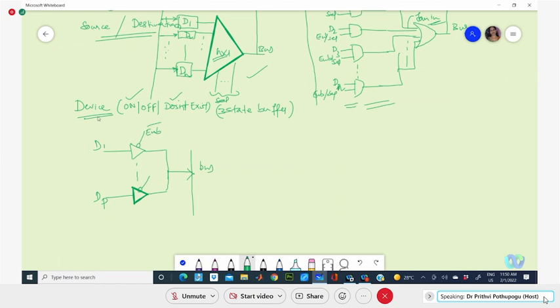And this tri-state buffer is used where, say, if we don't want to have any influence of any segment or any portion of the circuit in the total top level design, maybe we try to take the three-state buffer in the sense that when it is not used, not enabled, it won't be appearing in the circuit performance. That way of isolation, if we want, maybe this three-state buffer we need to take.